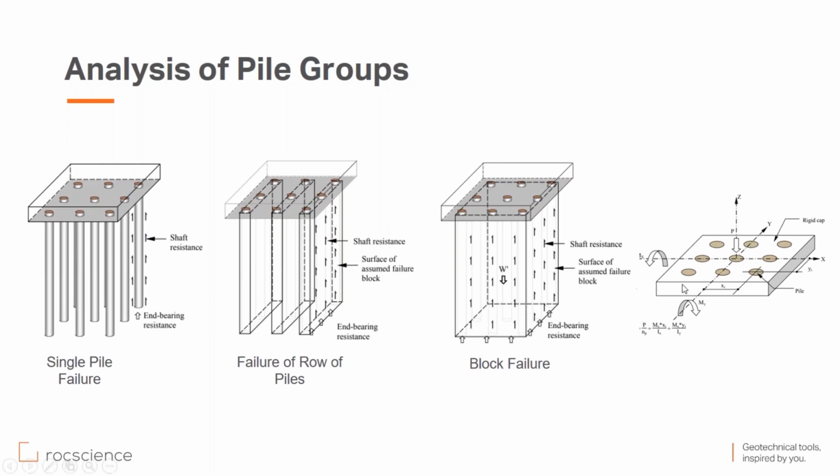The groups may be under a pile cap, which is subject to a vertical load, shear load in both directions, and bending moments in either direction or both directions.